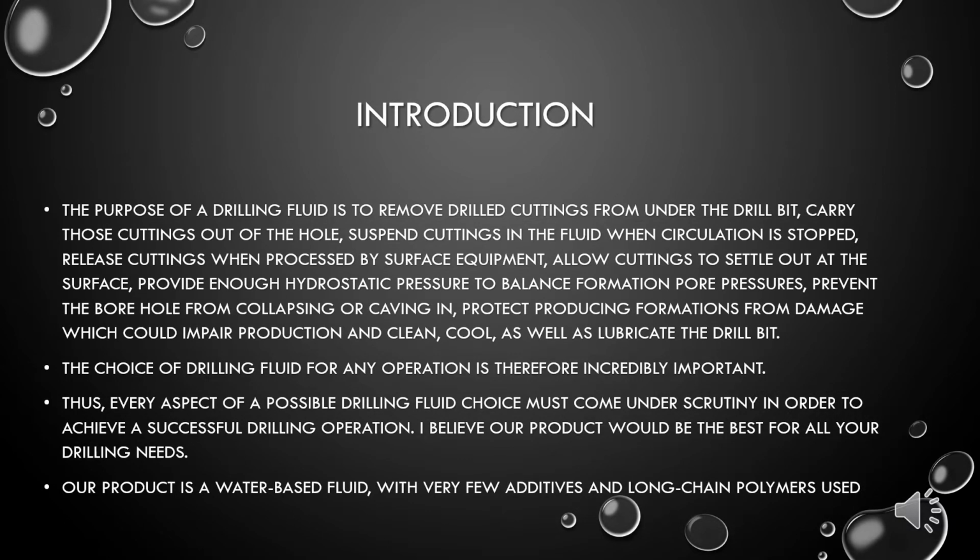The purpose of a drilling fluid is to remove drilled cuttings from under the drill bit, carry those cuttings out of the hole, suspend cuttings in the fluid when circulation is stopped, release cuttings when processed by surface equipment, allow cuttings to settle out at the surface, provide enough hydrostatic pressure to balance formation pore pressures, prevent the borehole from collapsing or caving in, protect reservoir formations from damage, which could impair production, and finally to clean, cool, as well as lubricate the drill bit.